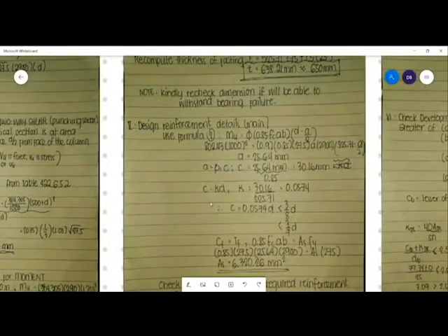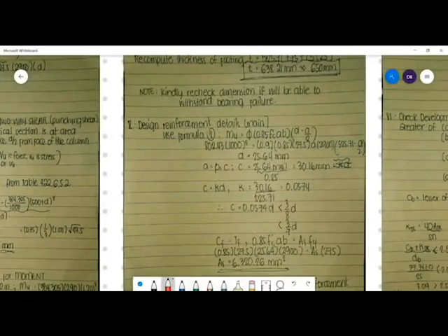Going back to the problem that we have here, before we proceed to solving the required steel area, we know that c is a fraction of d, the effective depth. You will notice that we already used 525.71 as our depth.